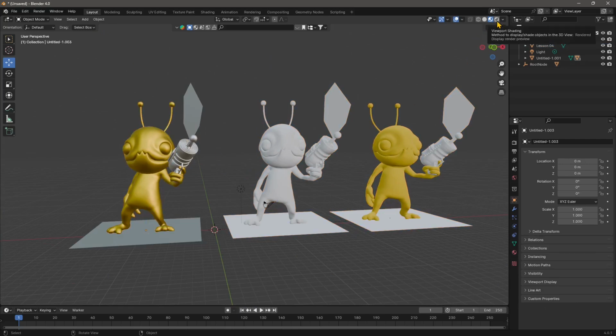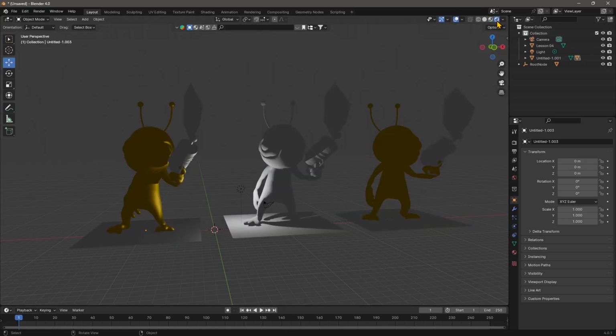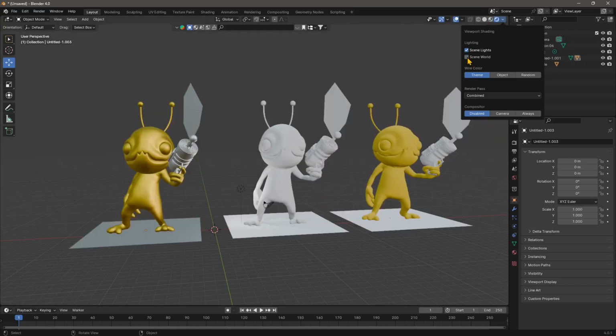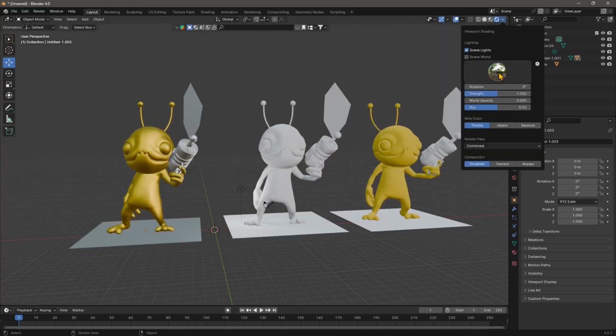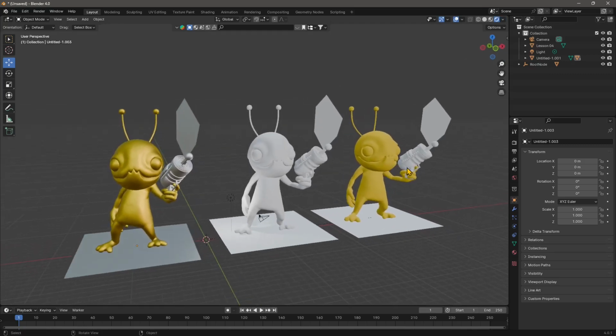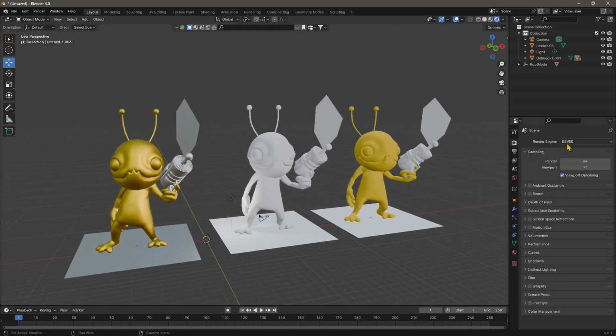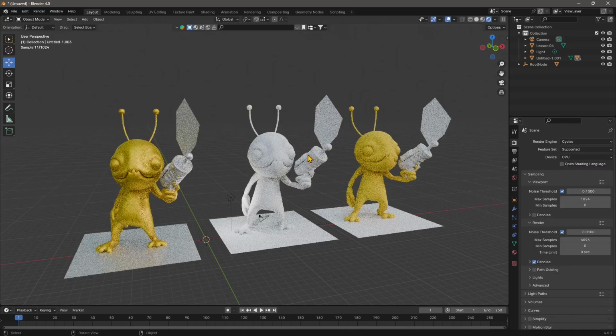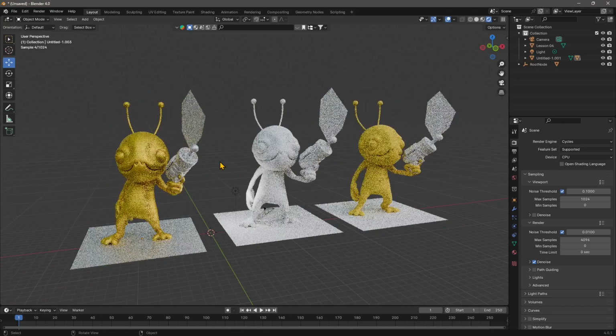And then let's move into the last one. This is the render. So I'm going to choose here to render with the standard HDRI. And then if I want a more advanced renderer, I can go here to the render settings and change it to Cycles. Cycles is the render engine in Blender. So we do have nice results already, but the problem here is that we don't have the textures. So textures are not directly applied. We need to create or customize the material inside Blender.